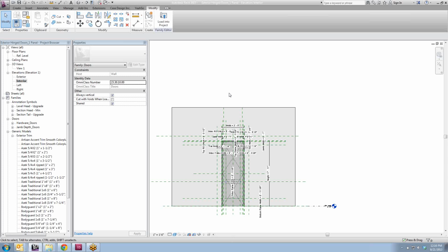You'd order a door with probably a 2x6 jamb, and then you'd have a drywall extension or some kind of extension, right? But you need the trim on both sides. So if you grabbed the Revit family for a 2x6 jamb door, one side of your trim is going to be floating in the middle of the wall, whereas you want it to actually be offset, like 5 inches or whatever.